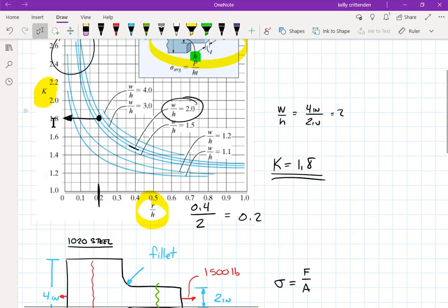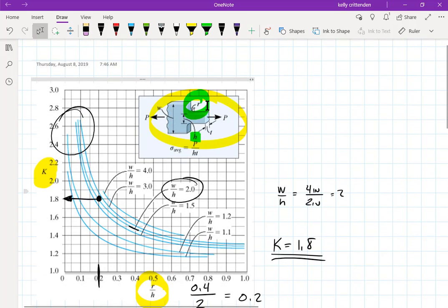And you take that stress concentration factor and just multiply by the stress that you would calculate just the way we've been doing for the past 10 weeks. So they're really easy to use, and they do give you a pretty good estimate of this larger stress. And that's totally legitimate.